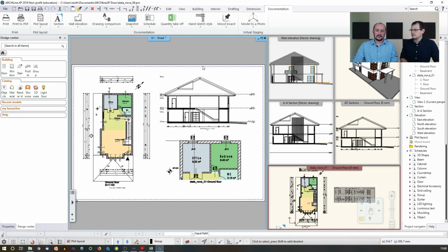So to create multi-page PDFs, we can actually stack multiple layouts into the same content using the print queue. But before we do that, let's just create another page onto this layout, and we will assemble them. So we will go with this one, and we will prepare a new plot layout using this plot layout tool again, and prepare plot layout.